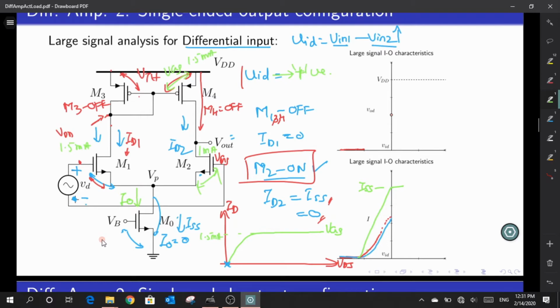So now what's supposed to be changed such that the M4 is also trying to take only 1 milliampere of current? The VDS value. You see, if the value of VDS is within this range, it has to accept this entire 1.5 milliampere. But if the VDS of this particular M4 is reduced, then it is capable of accepting the reduced current even though the value of VGS is equal to this VGS. So the way I can reduce the current through M4 is by stepping down the value of VDS to a small value such that it accepts that 1 milliampere current through it.